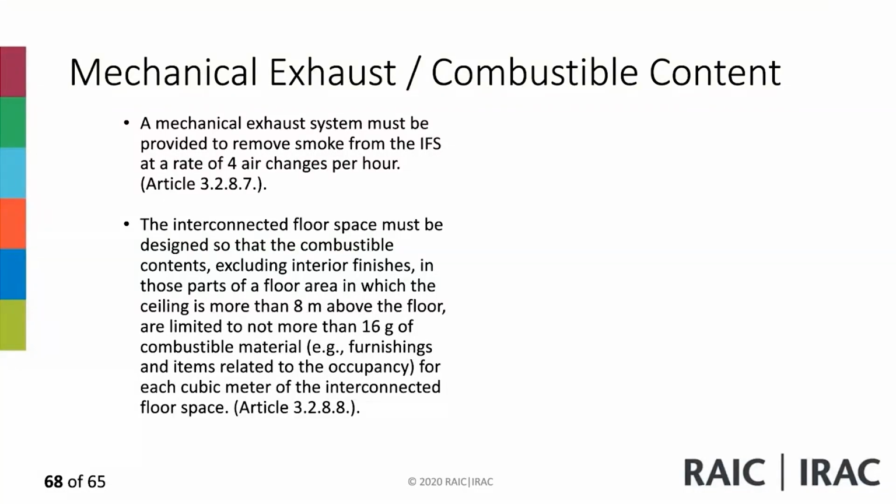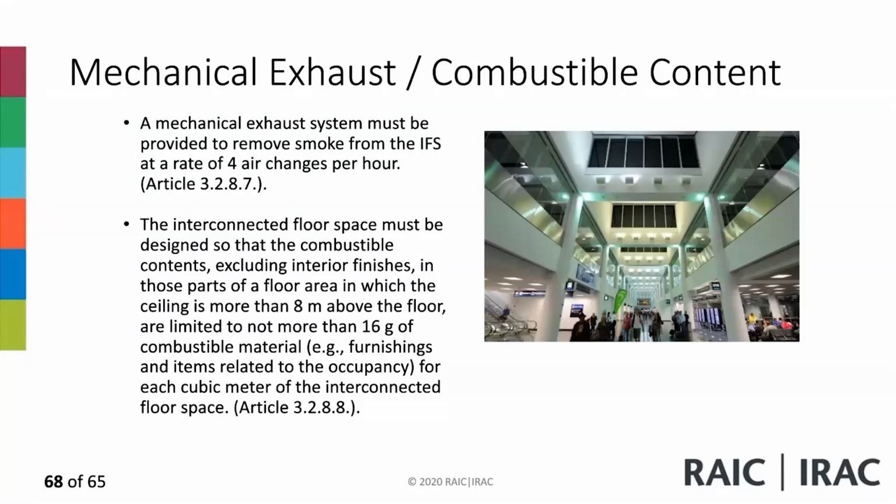So there is a limitation on combustible content, especially when you have a high ceiling. You don't want to pile up the whole space with combustible fuel, and then none of the systems that you have in place will work for you because of the sheer amount of fuel loading in it.